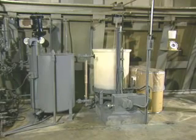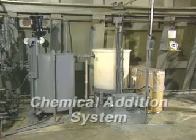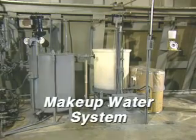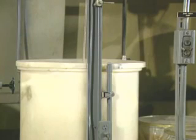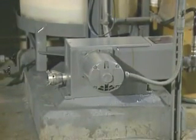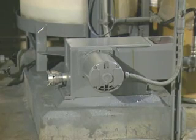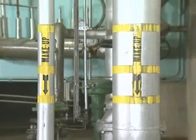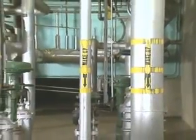Two additional systems are normally associated with the condensate and feed water system. They are a chemical addition system and a make-up water system. The chemical addition system may be connected to the condensate system, the feed water system, or both. It generally includes pumps and associated equipment for adding chemicals such as hydrazine to prevent corrosion and ammonia to control pH. The make-up water system is connected to the main condenser's hot well.